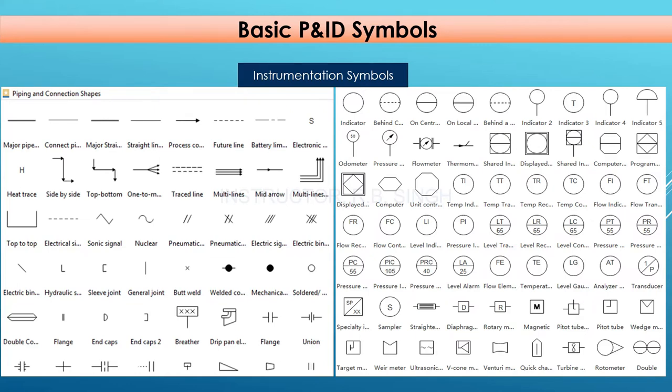Then again for temperature instruments. From the P&ID we must know this is the temperature gauge, this is the temperature transmitter, this is the temperature element. That can be clarified from the P&ID, because whenever you do the material requisition of any particular item, you must know about that item in the P&ID.